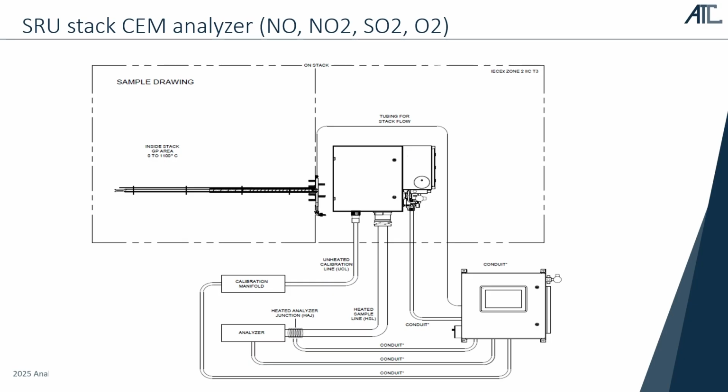In our case, the analyzer is just a small part, and the remaining parts of the solution are this probe and the sampling conditioning system, also with an auto-validation scheme to do a daily check of zero and span. This probe was not developed by us, but by MNC in North America solely for this process. Everything is kept hot at 190 degrees C, so we avoid all the cold spots because otherwise we would have a problem with sulfur. We had to be careful about how to provide a good, hot sample to the analyzer.